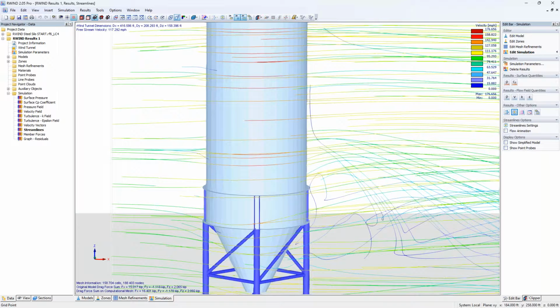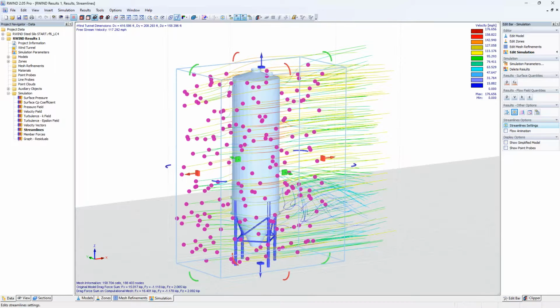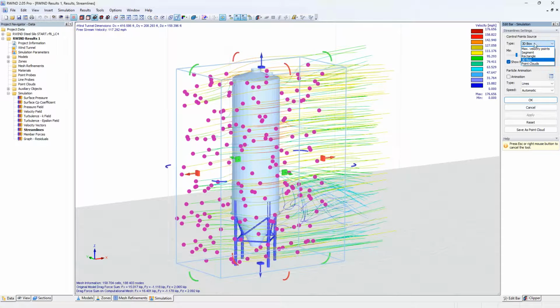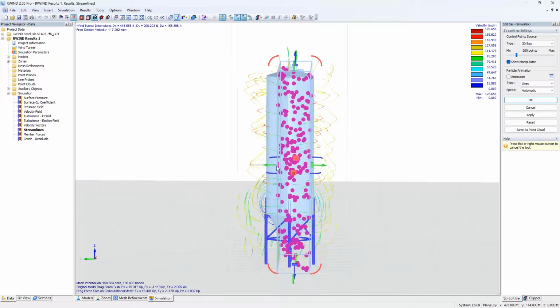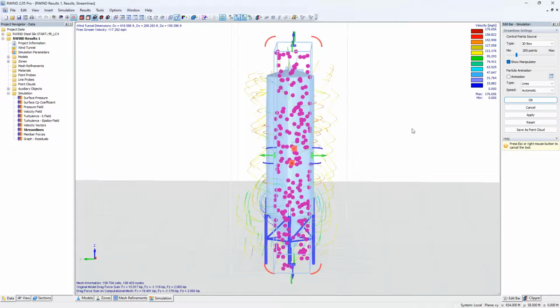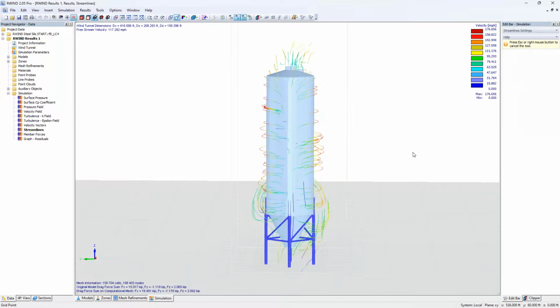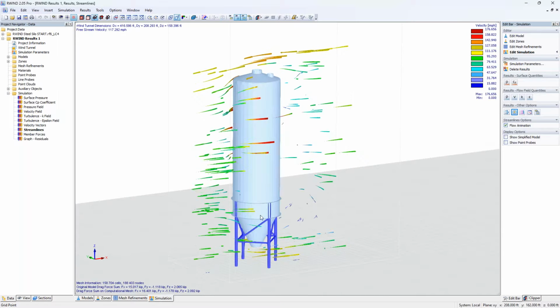This is going to show the particles that allow me to study the airflow as it moves through this tunnel. And we can adjust the streamline settings here. Under the drop down up at the top, we can change this to a segment, to a rectangle, or currently we have it set to a 3D box. Additionally, we can rotate this around and graphically make modifications to the size of our 3D box. If we wanted to set that to something more narrow, we could rotate it. Once we click OK, this will adjust those particles and we can activate the flow animation.